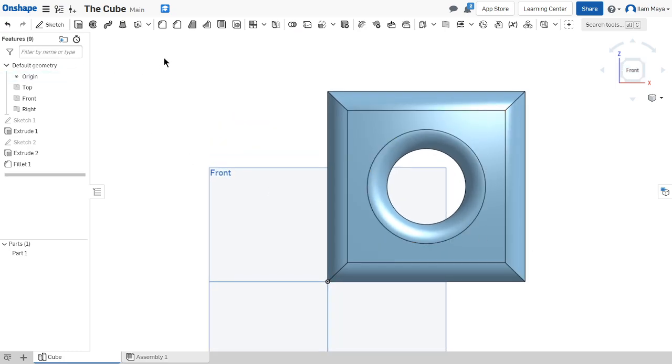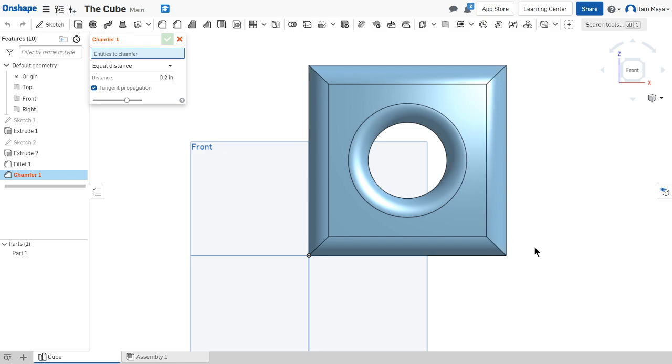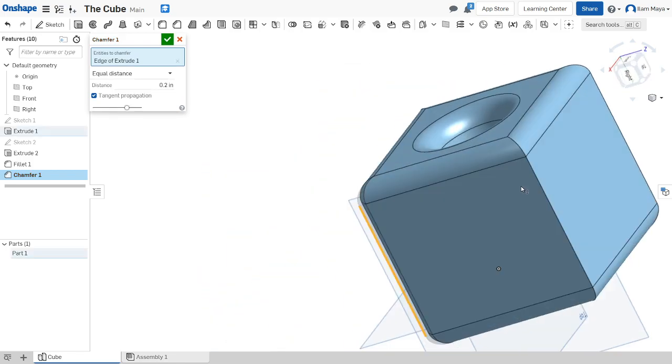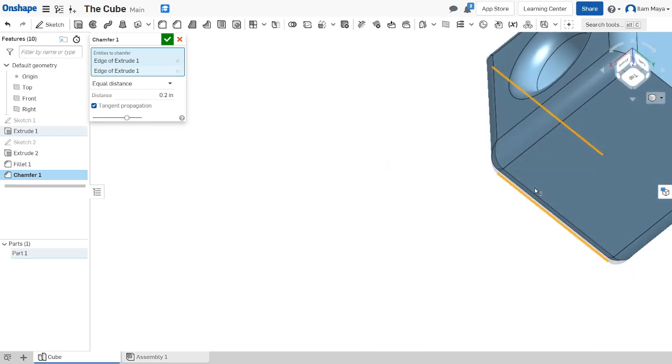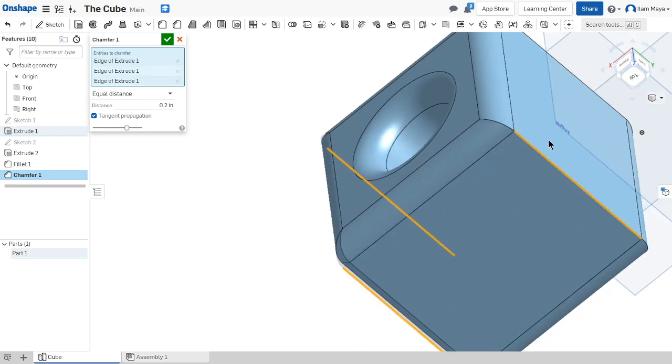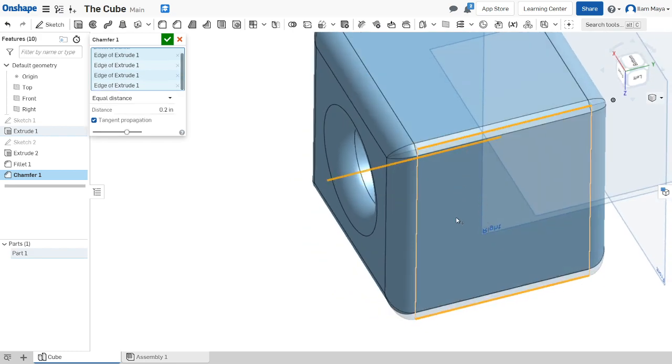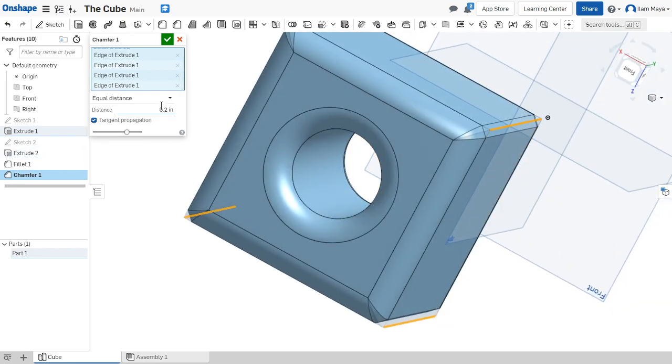One last thing I'm going to show you real quick is this thing called a chamfer. Expert 3D modelers, you know what that is already. For those of you who don't know, you're just cutting off the corners, but sharply. You're not rounding it off smoothly like in a fillet, you're cutting it off sharply. So I can click on each individual corner, and then it's going to cut the corner and make it kind of slanted like this. I'm going to make it bigger so you guys can see better.